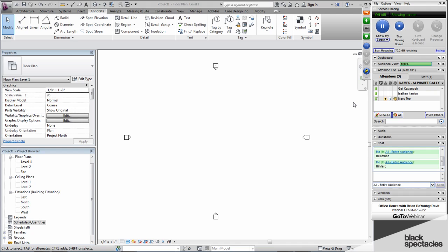Then you would have a completely separate building file where you would actually construct the building, if we're talking about a single building. Now, the projects that I work on are often multiple buildings on the same site. So we typically have a site file and then say building A, B, and C, and maybe a separate basement.